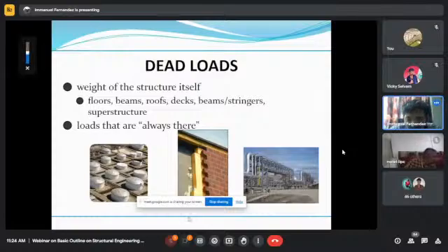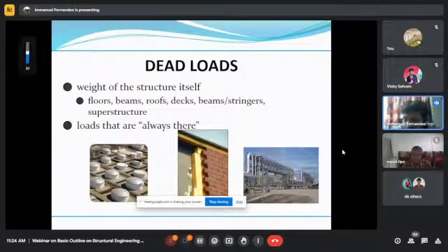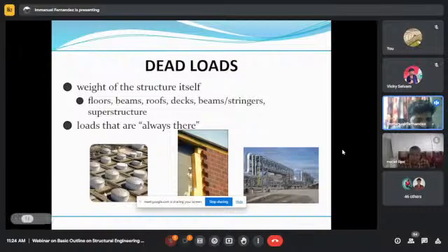See this image, these are all tanks. The first image I'm showing, these are tanks. These tanks are basically used in storage. Like after you get a byproduct, after you get the crude, the crudes will be stored in separate vessels, and the petrol, diesel, everything has to be stored, right? After refining the crude, we have to store. So we have the tanks here, and every tank is kept at a very good distance, so that even if a tank spills, the liquid gets retained within the particular dike area. We never allow the liquid to go beyond that in case of any spillage or any accident.